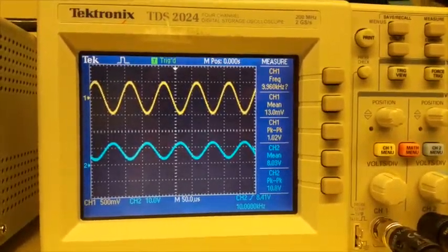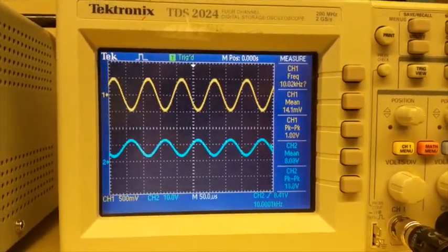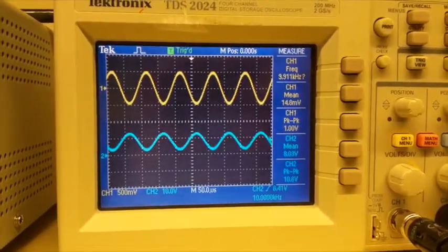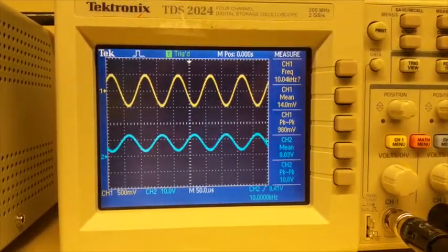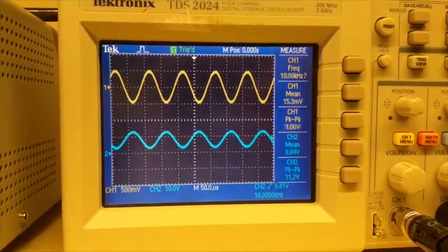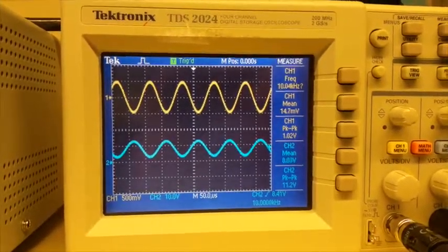VC has a much greater amplitude at peak-to-peak voltage than VN because there is a gain. The gain is of relative magnitude RC over RE, which is about 10, which, as you can see, the peak-to-peak voltage of VC is about 10 times greater than that of VN.